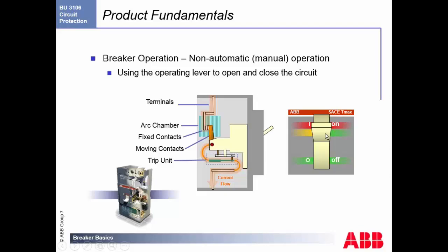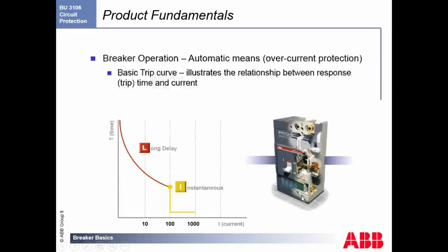download. When you flick the switch, you'll notice that our moving contacts pull off, which then disconnects the circuit completely from the power coming into the building. This means nothing down the line has any more electricity, there's no more current, there's no more voltage, and it's safe to perform maintenance, or you can go and find out if there's any damage to your products down the line.